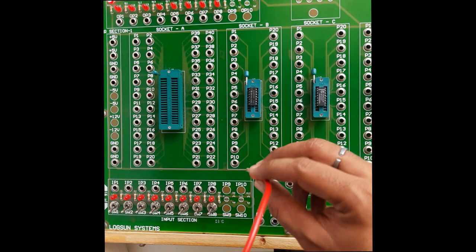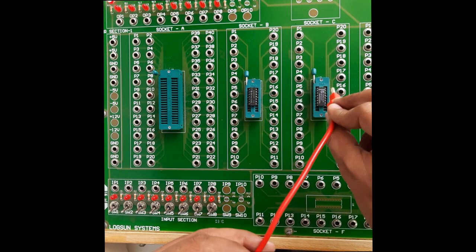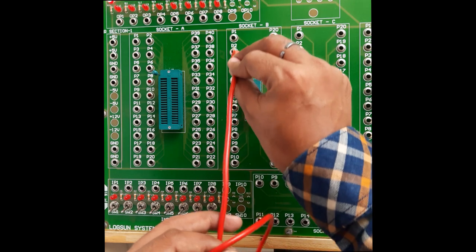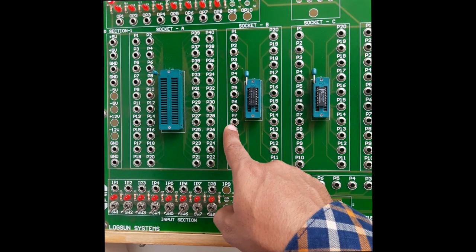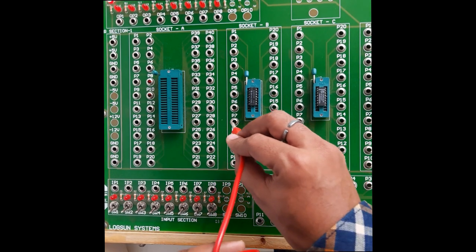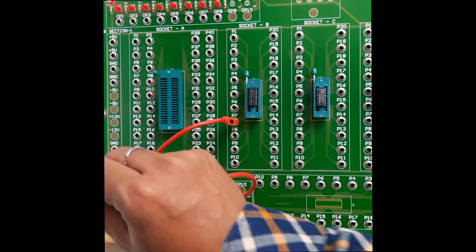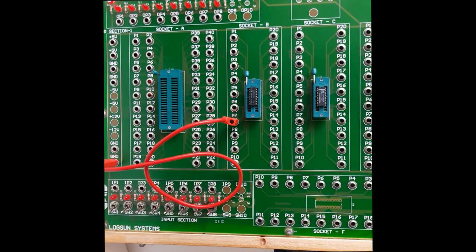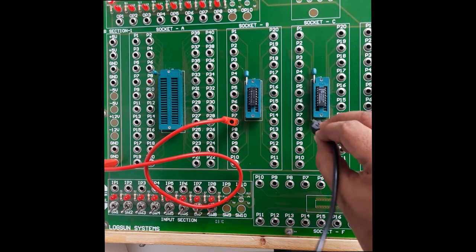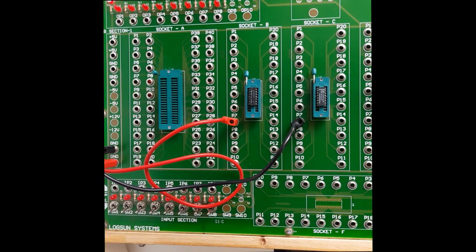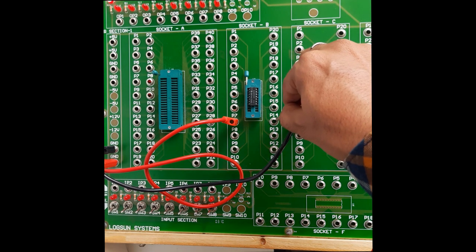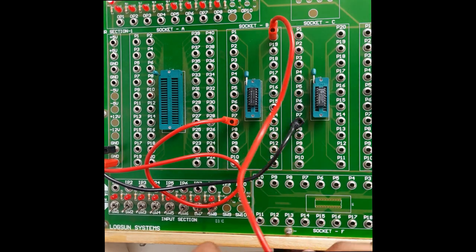Now the very first thing you have to do is connect the ground and VCC cables. I have used the first slot, so it is easy for your calculation, at least for the left side, because it is directly marked 1 2 3. Here pin number 7 I have to connect to ground. Then the second IC is this one, again pin number 7 is used for ground. Now VCC or +5 is on pin number 14. After 7, this is my pin 8, and the last pin is nothing but VCC.